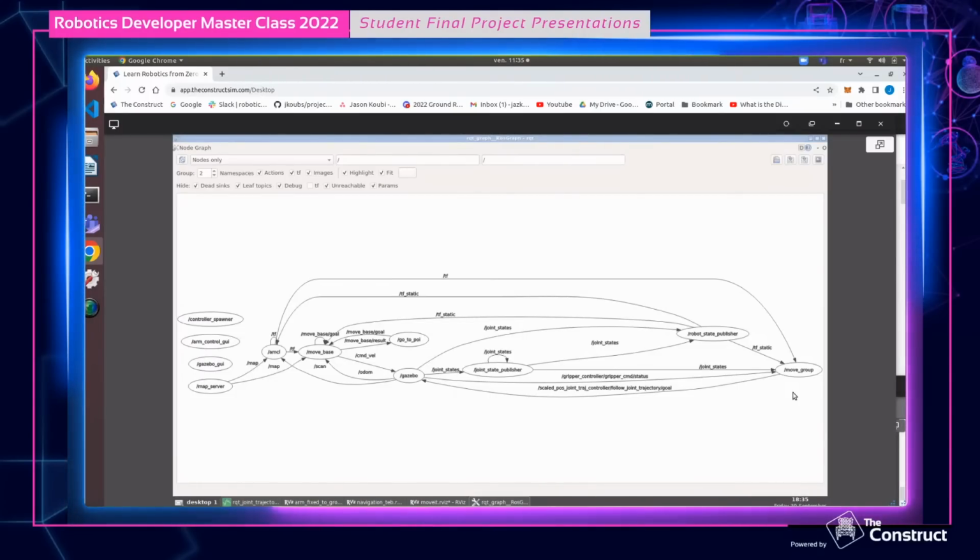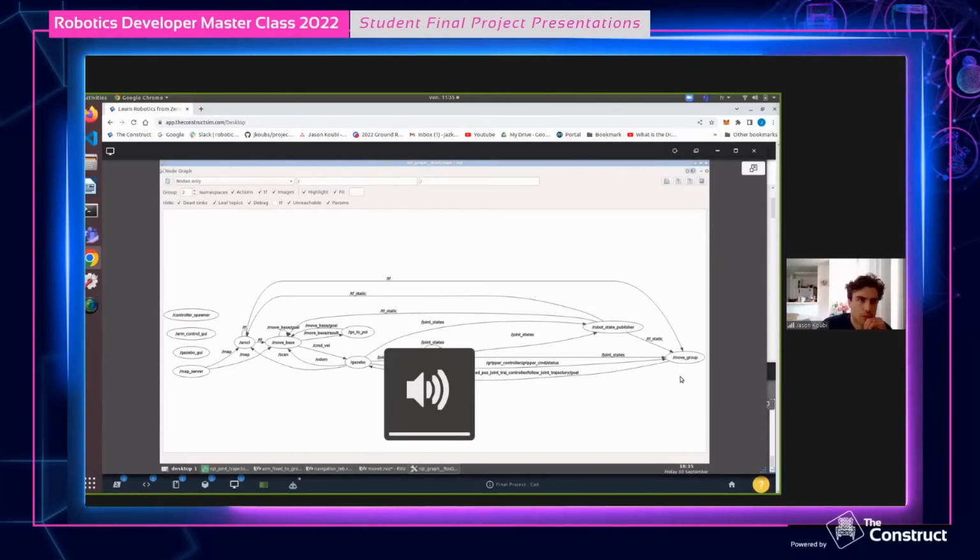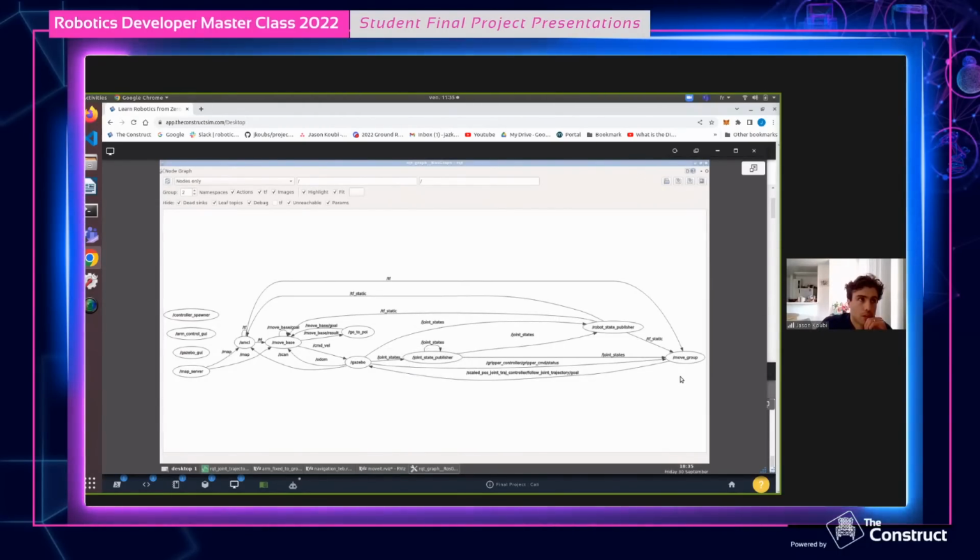In the configuration of MoveIt, you can define what it is attached to. And actually, I think it is already done, probably, because otherwise it would have collided. So it's defining this as a collision object that it can handle. It's not planning that part, but it's taking it into account for collisions. You are passing the URDF of the full robot to MoveIt, right?